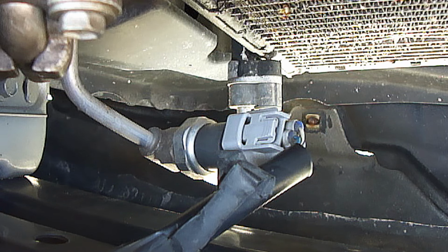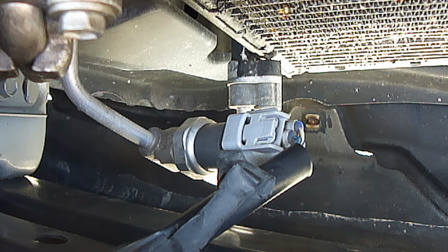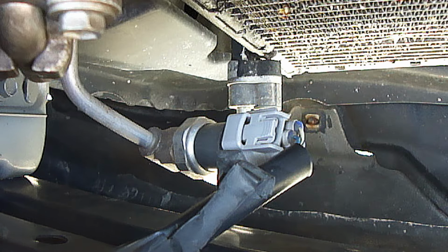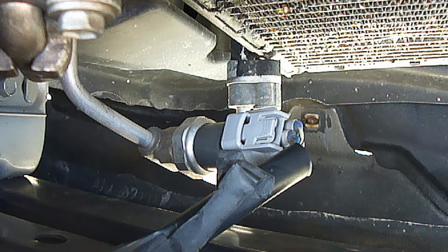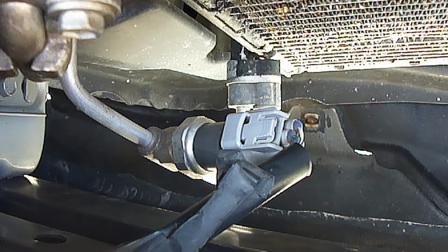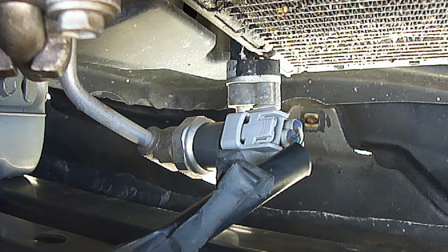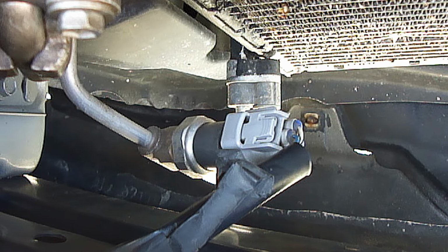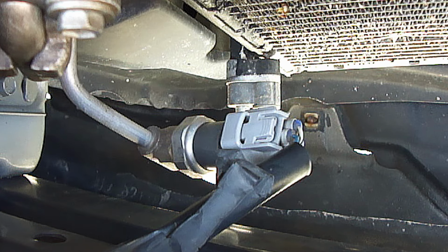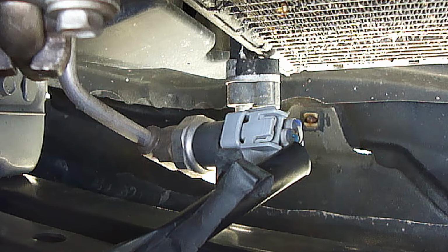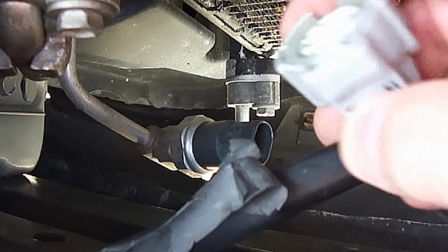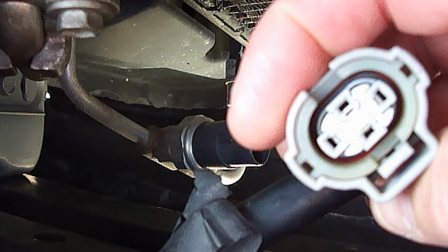Now I'll do an actual bypass test. The outside temperature should be at least 60 degrees Fahrenheit to be sure the air conditioner system will operate. This pressure switch is good, but by disconnecting the pressure switch electrical connection, this will simulate a failed pressure switch in the open position, causing an open circuit, which means the clutch will not turn. As you can see, this has four electrical contacts.